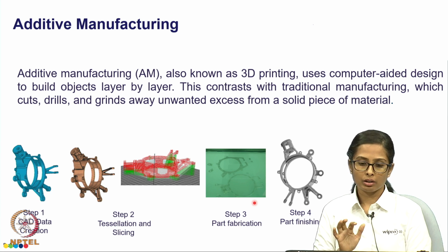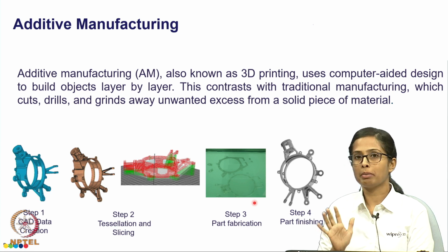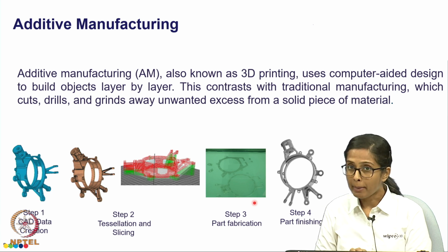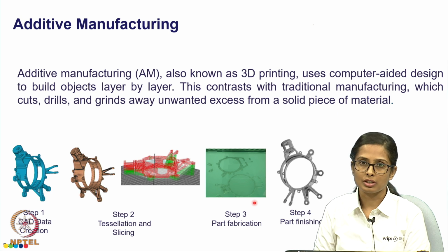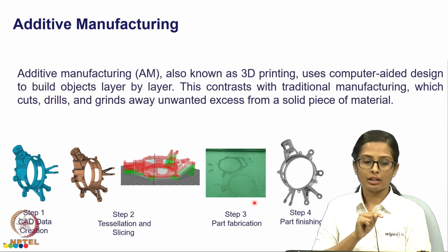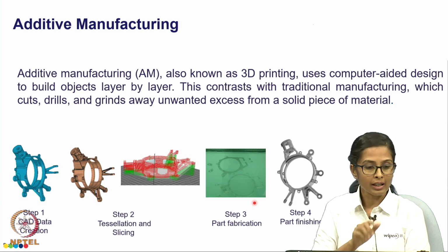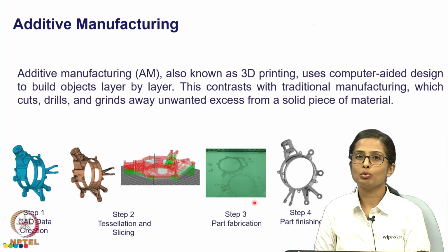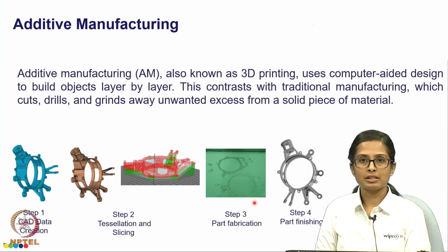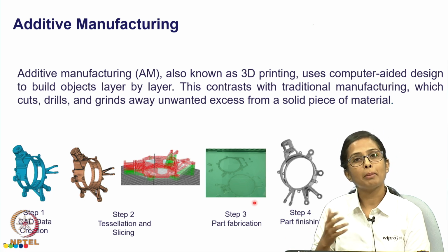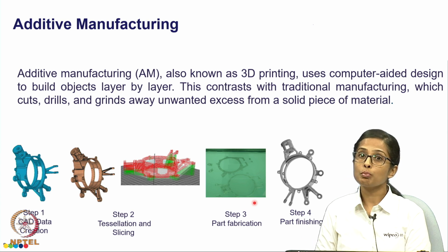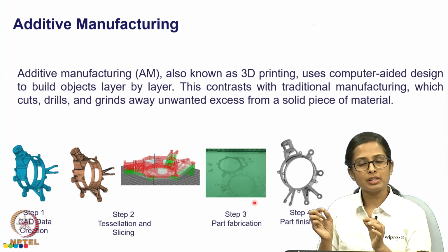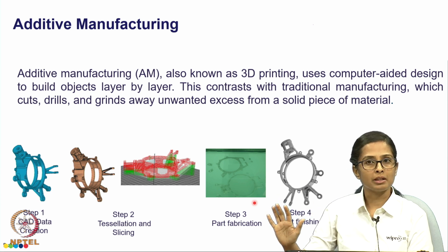So, then you do the actual 3D printing, but there is another step which is part finishing. So, the picture that you see there is an actual part, 3D printed part, but remember that this does not have the support structures, right. The green color support structures that you see there, they have all been removed. So, this we call as post processing or part finishing. In case of polymer parts, it is possible in many cases to very easily remove these supports and use them as end parts.